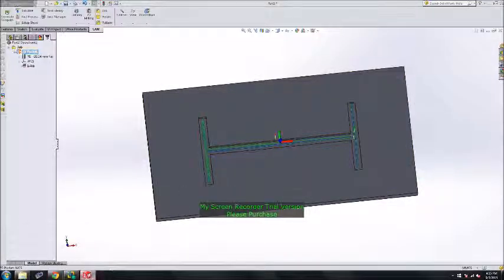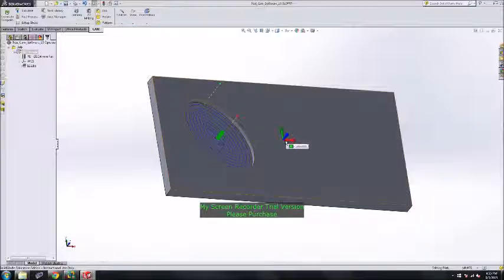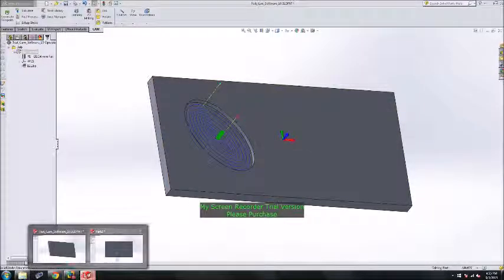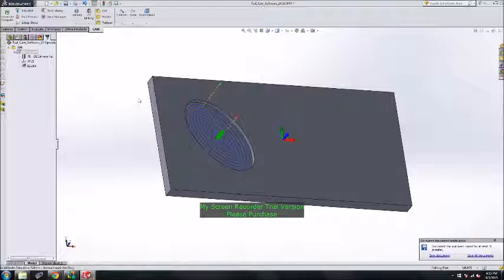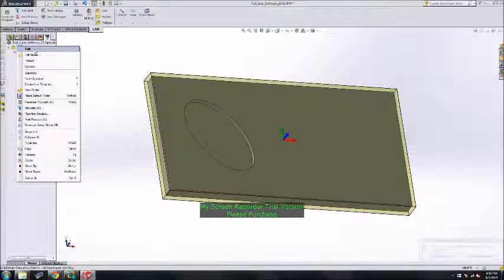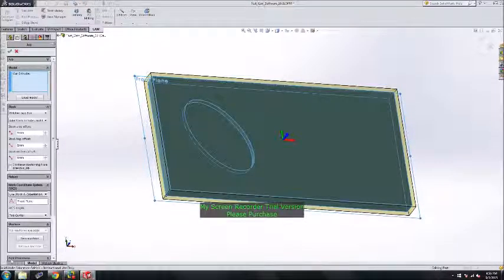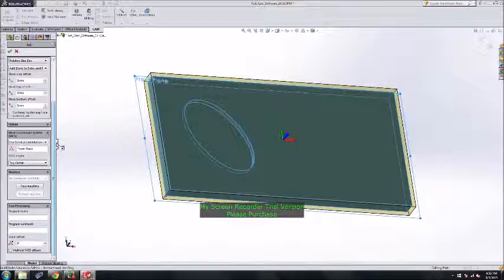And as you can see, the WCS coordinates, the work coordinate systems, are at the center in this profile. But you can always set it to any one of the vertexes, any one of your desired vertexes. To do that, go to Job and say Edit. Go down, and in the tab where it says Work Coordinate System, change the settings. I'll use origin and orientation.